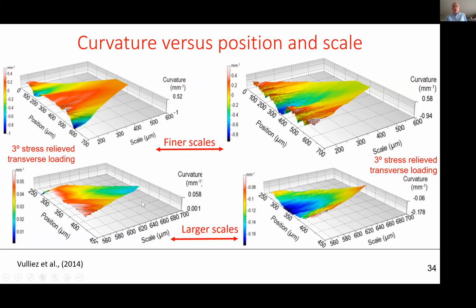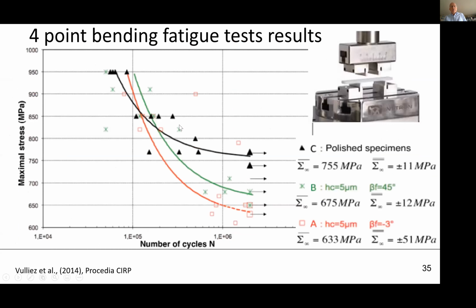In this, while we were working from 3D measurements, we extracted profiles in the direction appropriate for the loading. And so we can see these patterns of position along the profile, scale, and then curvature in the vertical. So they make rather nice looking little diagrams, and they're also kind of revealing. Now the fatigue tests are extensive. There were, I think, 80 surfaces that were fractured in 4-point bending.